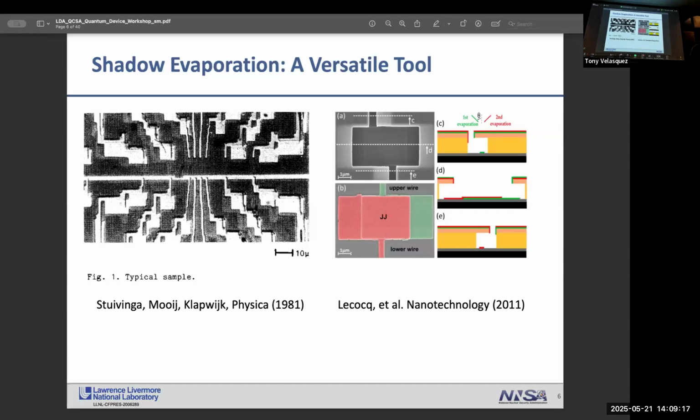On the SEM subject, you said that the bottom layer aluminum is epi, and then the top layer aluminum is deposition. No, in this case, no. Because they look similar. Yeah, exactly. With any material system, as you grow thicker films, you develop grain structure. In the thinnest films, you don't see a visible grain structure. That's why it looks smooth. It's the same deposition process. It's just thinner.